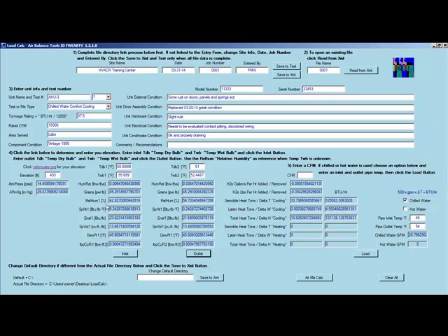And so now we have a grains. In this case, there's no dehumidification happening at the chill water coils. They're removing sensible heat, not latent heat. In this case, we want to match our grains. We got 29.145, 29.100.